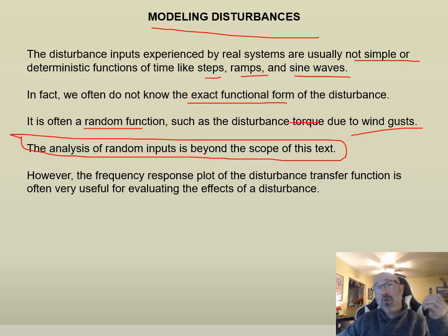A lot of times, how we deal with these disturbances and model them in is to analyze them separately. Take a look at your system as a whole in a controlled environment where you don't have any outside sources. Call this your background control variable. If you have the system running with no outside sources, no wind, no nothing, in a vacuum, in a clean room, whatever it might be, to make it completely controlled in an unrealistic environment, and you have that information, then you run the same experiment in a realistic environment where you have noise, wind, dirt, dust, whatever it may be, and you can compare those two signals.